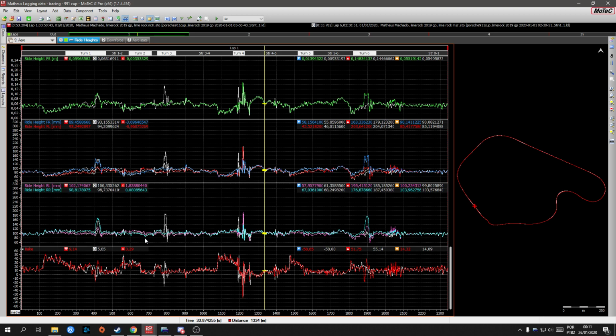Oh yeah, one last thing that I want to emphasize is when you're making a change to the car, let's say, oh, I'm going to have the perfect aero of the car. Don't forget about the other aspects of the car, because if you change one thing on a race car, you're going to change another thing as well. Because changing ride heights changes load transfer, and load transfer dictates a lot in the behavior of the car. Changing tire pressure is going to change your aero, so be wise when making changes, and try to minimize your changes as much as possible.